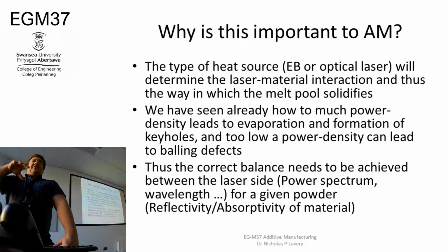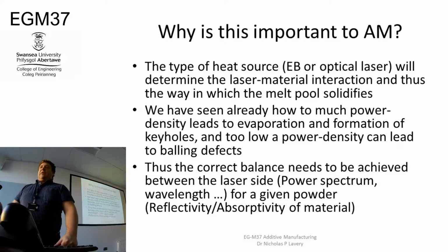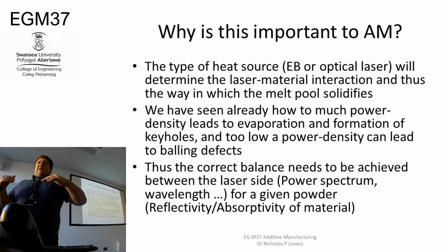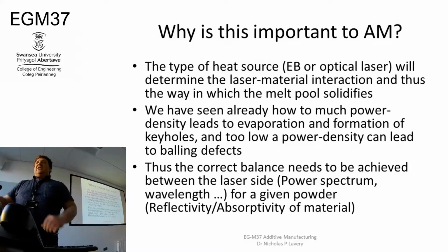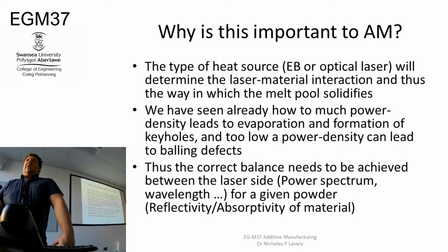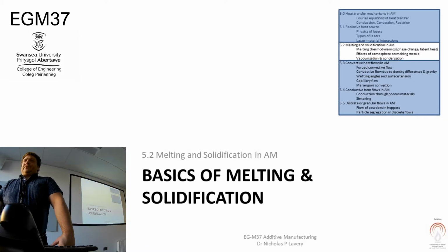But also, if your power density isn't right, you can also have balling effects. So if it's going too fast with not enough power, you'll end up heading towards balling effects. So you need to get a balance, and that depends very much upon the heat source you're using, but also on the properties of the material, and also how it's cooled and how the gas goes over it. So all of these things combine together.